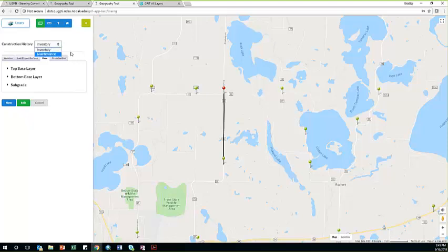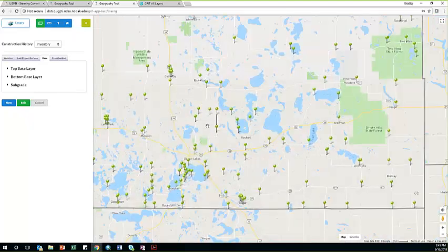Once all the data is entered and we have some pavement condition data collected from either the pathway van or other, it'll predict the future condition of the road. So you can pick out 5 years from now and see a map of what the condition of the road will look like. That new tab will pertain to all that information. We'll need some traffic data, some pavement condition data, and some structural information. And so that's where that'll go.